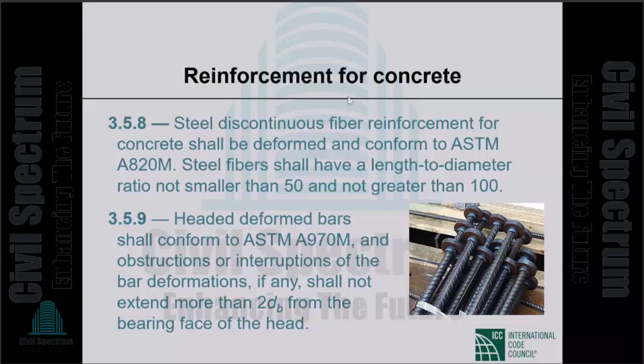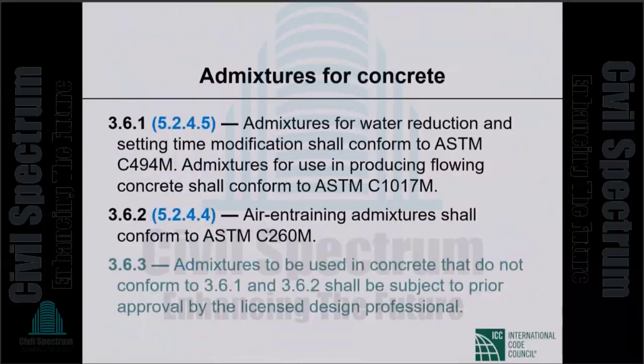Okay? So those are two important items that you do not find in BNBC 2020, the steel discontinuous fiber reinforcement and the headed deformed bars. Okay, that brings us to admixtures for concrete, admixtures for water reduction, and setting time modification shall conform to C494, very important ASTM specs.